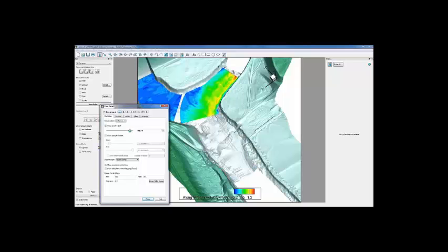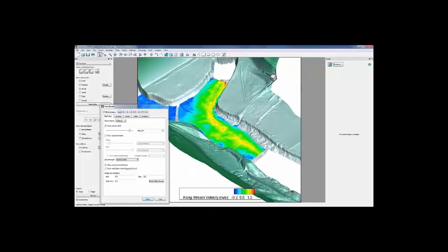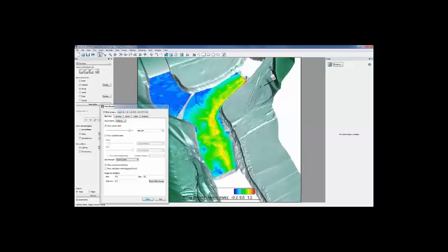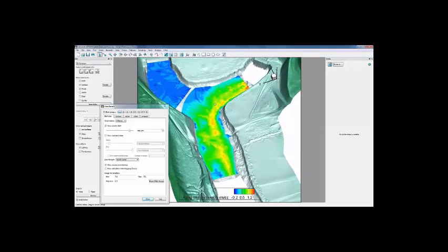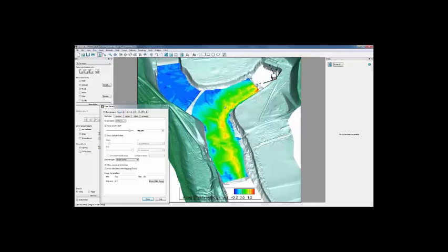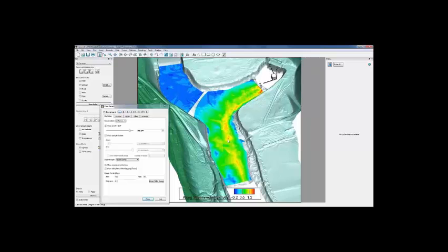You know, one application I think of is just hydrometry. It was mentioned that this is a velocity indexing site. Velocity indexing, for those who don't know, is a tool to get a discharge rating, a continuous flow record at sites where, because of backwater or regulation, a standard stage discharge rating won't work.